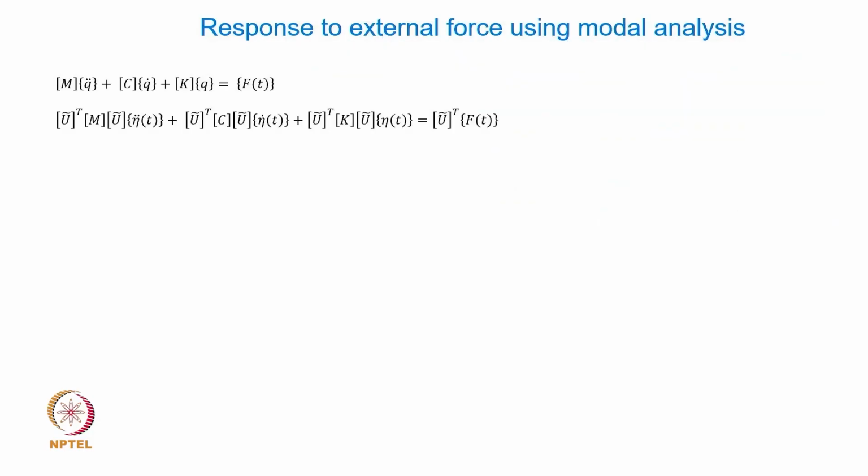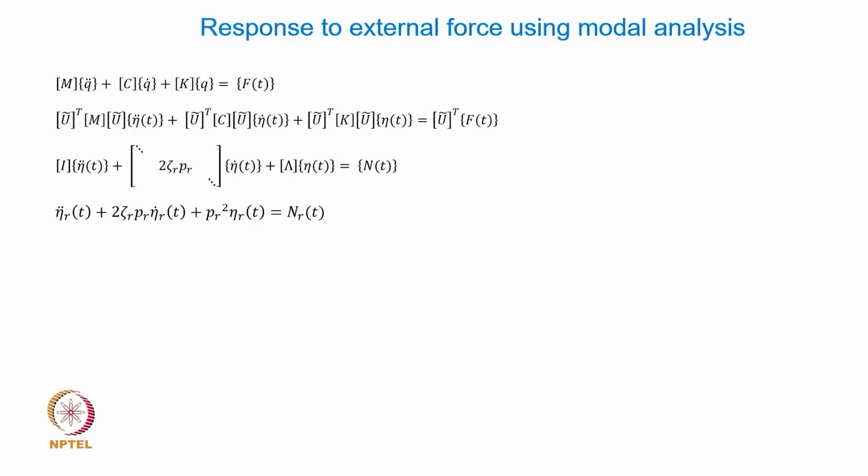So, we assume the system to have symmetric stiffness, mass and damping matrices. That is an assumption, of course, because only then will our orthogonality work. So, pre-multiplying, post-multiplying, converting into our principal coordinates etas, you get all of these. Now, in this case, pre-multiplying by the transpose of the normalized modal matrix will generate the generalized excitation force. These are generalized forces.